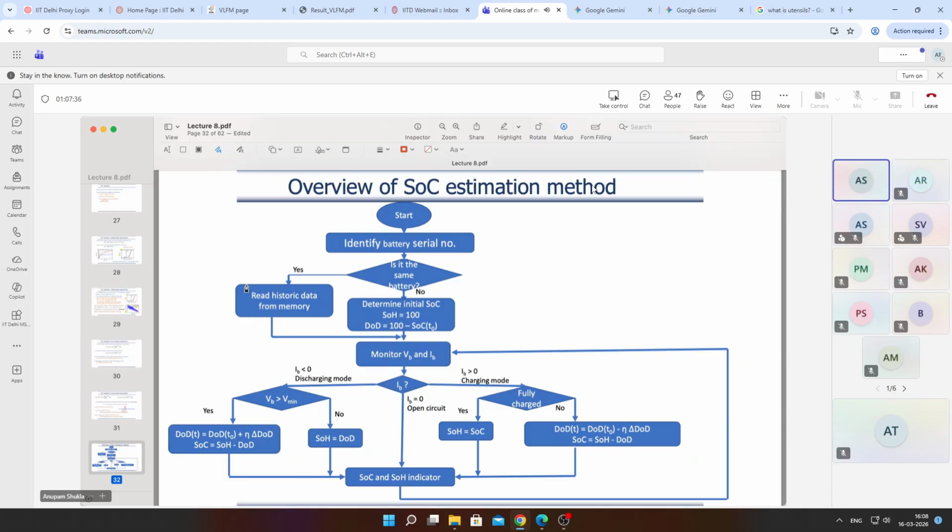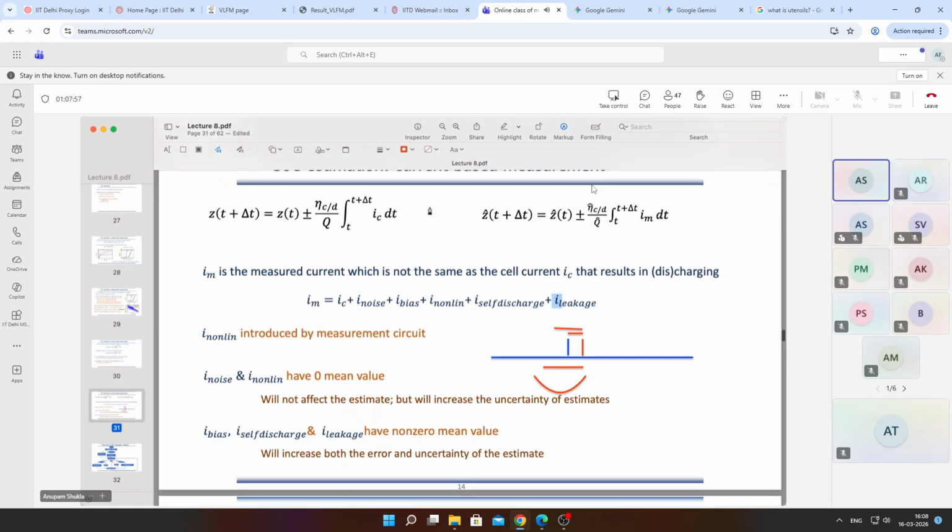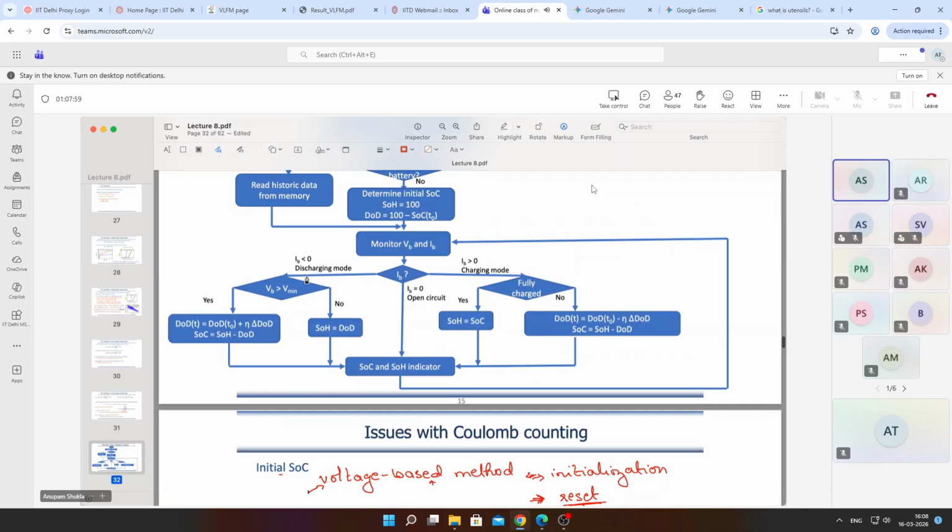Now, how is this delta DOD calculated? It is calculated similarly using this equation. Okay. Except that this was in terms of SOH. Actually, now you are only calculating the last term in the equation. So you just calculate, except this plus sign will become minus, and minus will become plus, because we're doing depth of discharge and not SOC. Okay. So again, we'll not go into the question why.